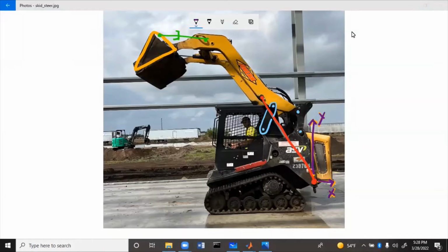So now we'll assign vectors to all of the links to get a vector loop diagram. We've got 3 loops, so we'll start with the bottom loop. So down here is our coordinate frame. We'll start there and go up along this cylinder, R1, and then we'll go from the origin up here. Say that is R2, R3, R4, R5,